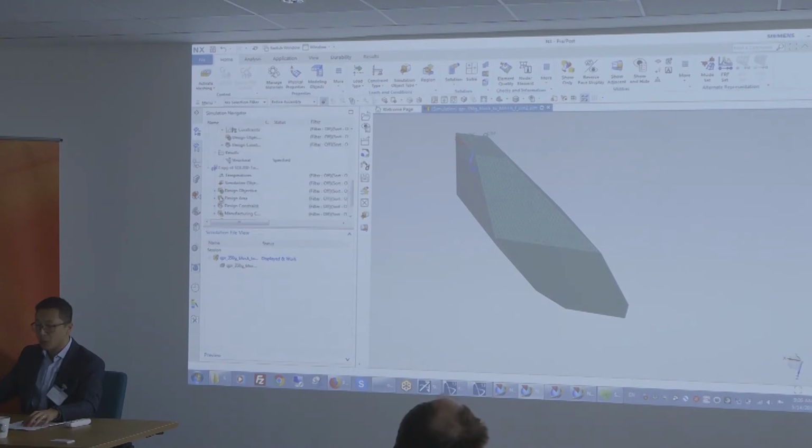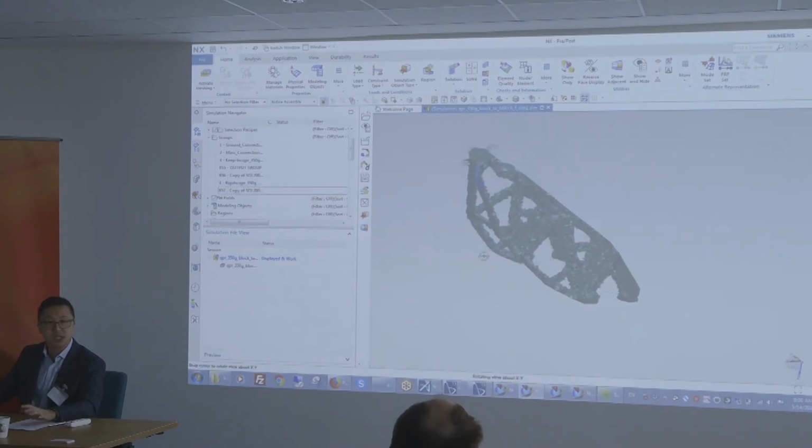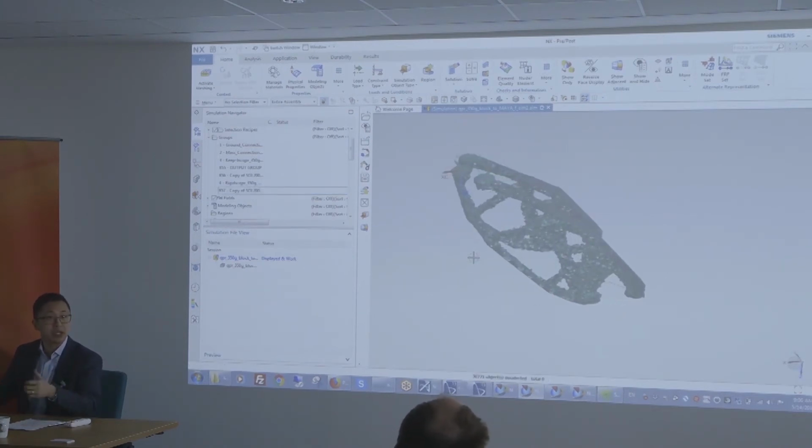But what happens with this one here is it's recreating a subcase or a solution with only the relevant elements. And again, at this time, it's not smoothed, so the validity of the results you'll get is questionable because they're sharp ends, but it'll give you an idea of what the weight is. That's always the difficulty, is where do you set your density level? Exactly, yes. That's always the difficulty with this. Mm-hmm. We do have best practices that we've used a lot with our aerospace customers, but definitely I agree with you. It is always a challenge. Do we keep less and smooth it, or do we take more and then trim it ourselves, right?